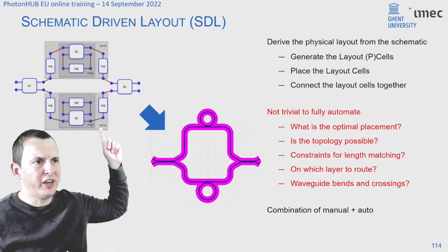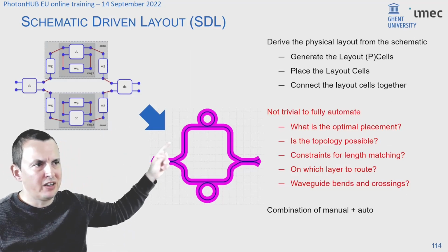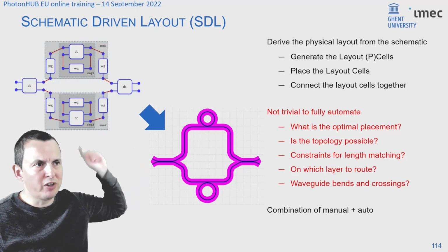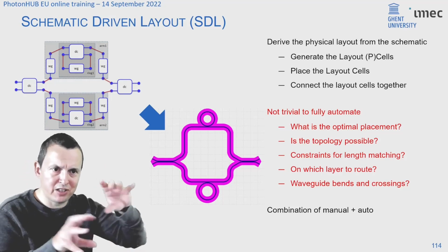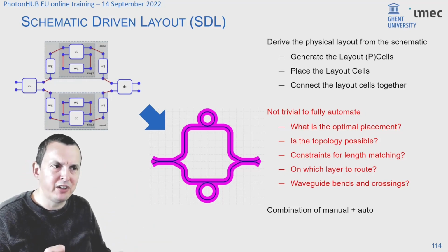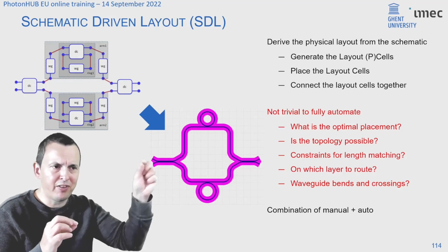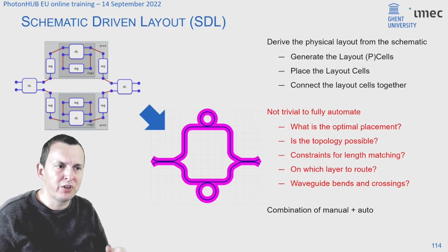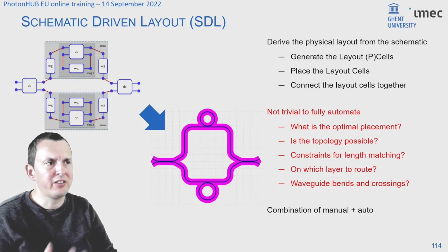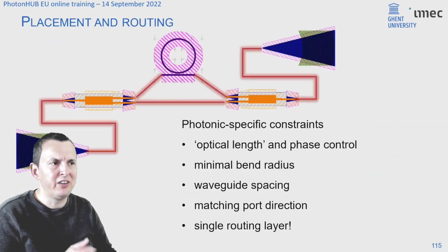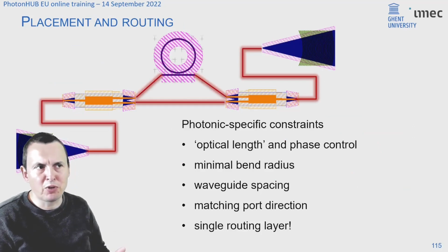Essentially, you take your schematic and you translate every building block in the schematic to a corresponding building block in your layout. And then either you can automatically place all the building blocks so that they fit together, or provide some guidelines like fly line drawings for the user that help you connect all these blocks together. And this is essentially becoming a place and route problem.